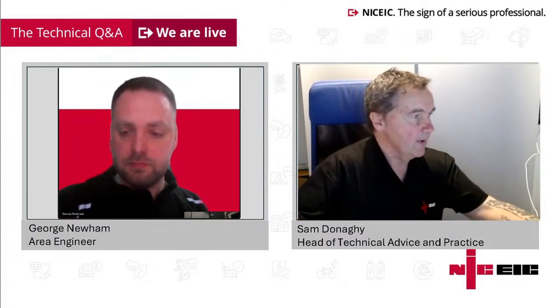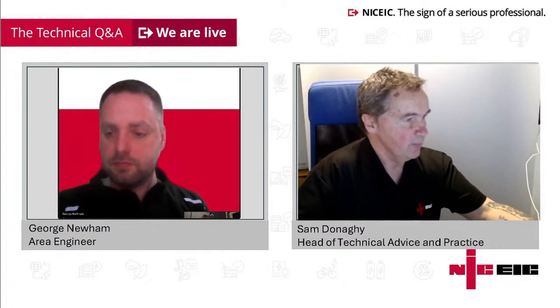We've got a few other comments that have come in. So I think the engineer that talked about a requirement for lightning protection has asked about client preferences. Is there anything I could do that would come back? I think you need to look contractually. If you're doing the electrical installation, you wouldn't normally be contractually required to provide the lightning protection system.